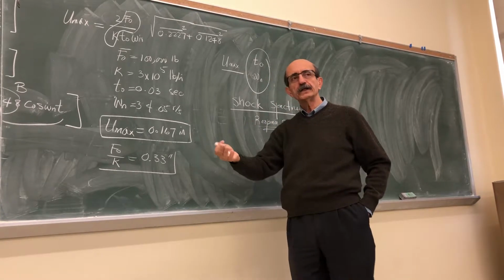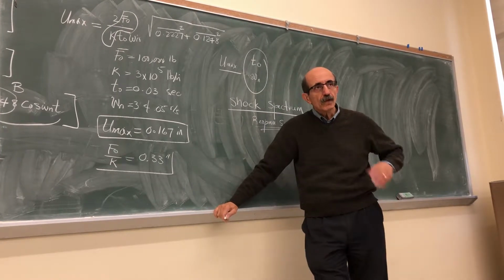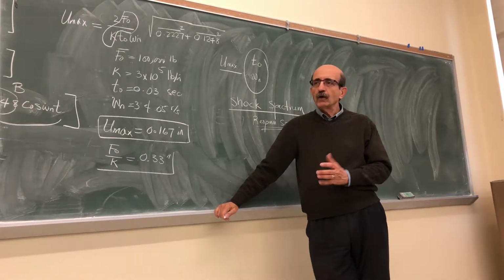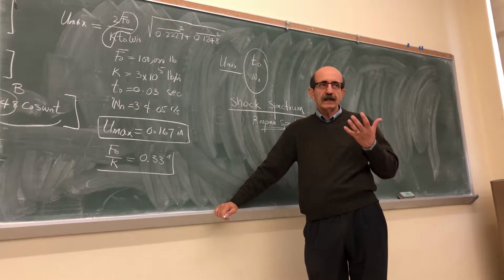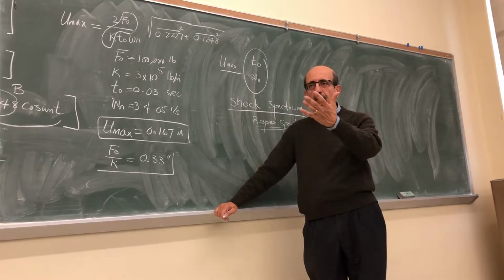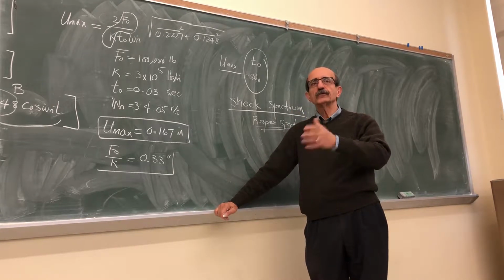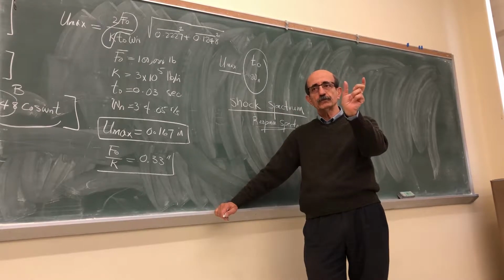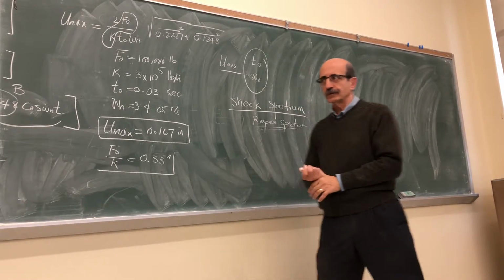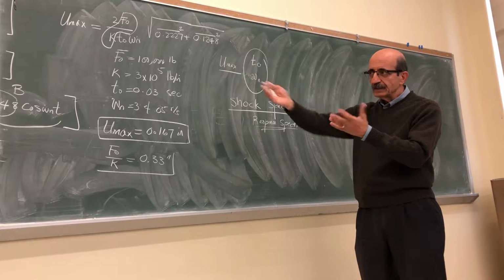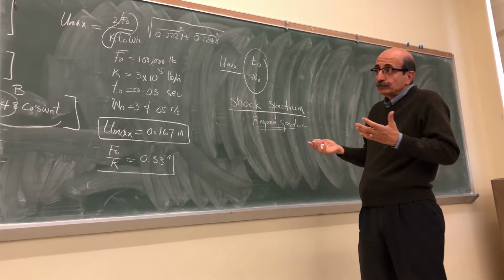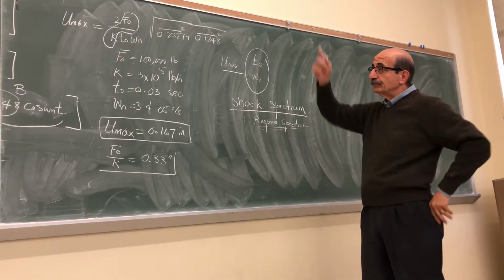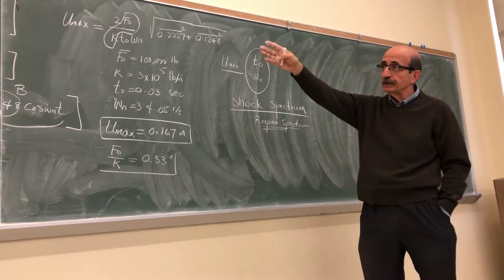Remember in the harmonic loading, to find the maximum response we had a tool. Maximum dynamic response is the maximum value of the frequency response function times the static displacement. We saw here that that doesn't apply, and in general we have to go through the pain of finding the maximum displacement for each region of loading.